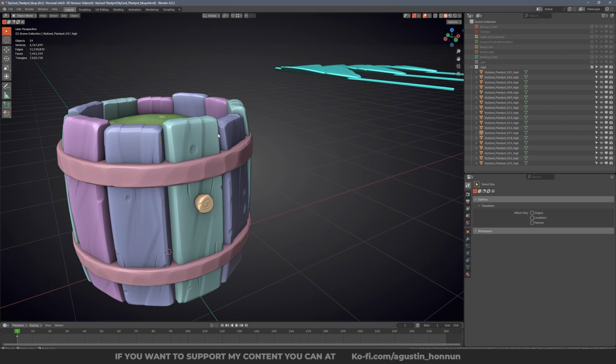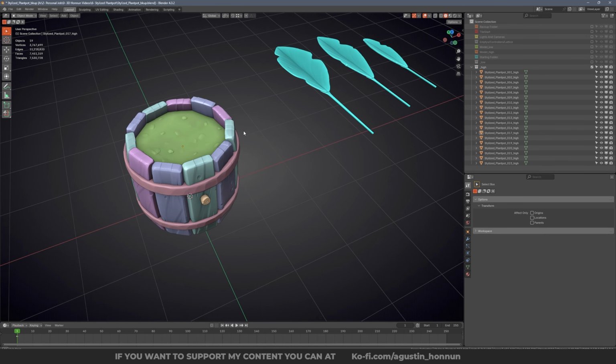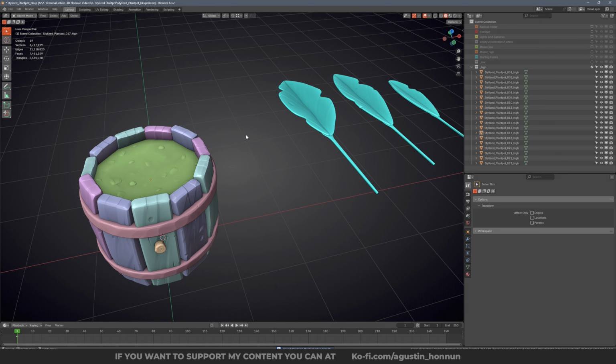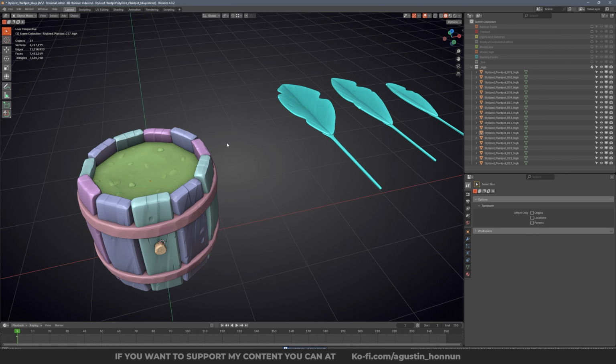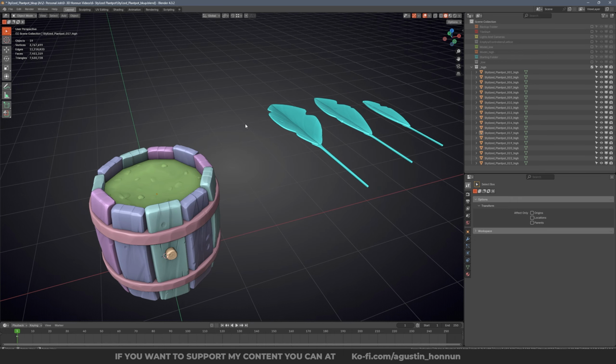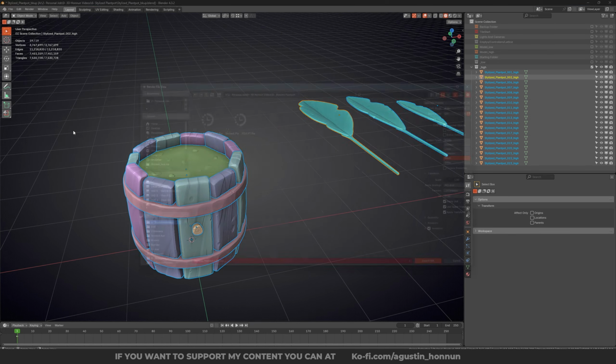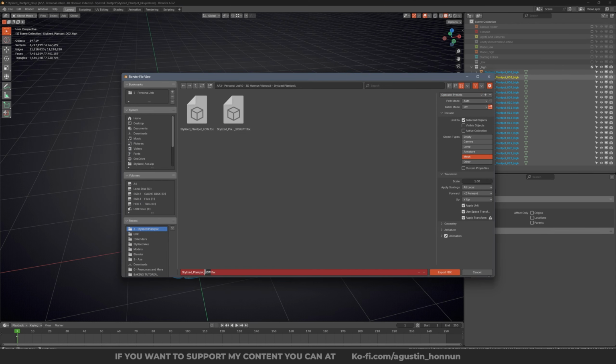This process is not necessary sometimes, because if you have good UVs, you can simply use the polygon fill tool in Substance Painter to mask the materials. But I prefer to use Vertex paint, since for me it's easier and you have more control over all of the painting process. So select now everything and go to File, Export, FBX, and here I'm going to call it ID map. Of course, you can export the same ID map as the sculpture. It's practically the same. Usually I prefer to have them as a separate mesh.